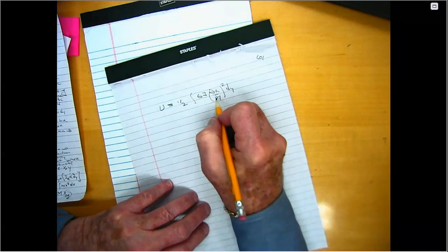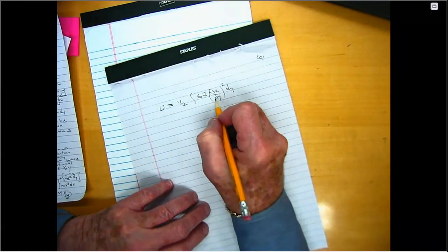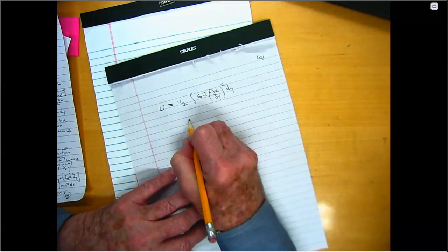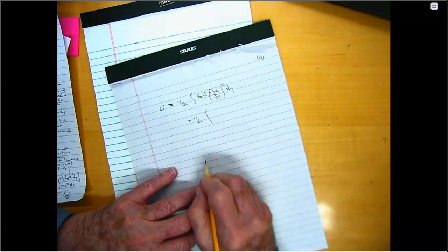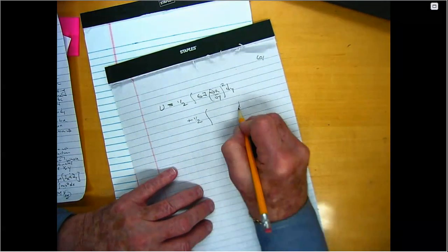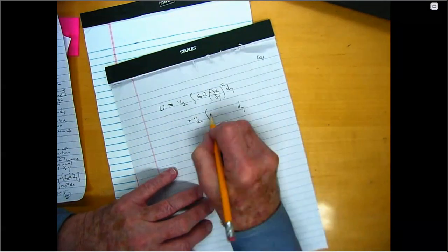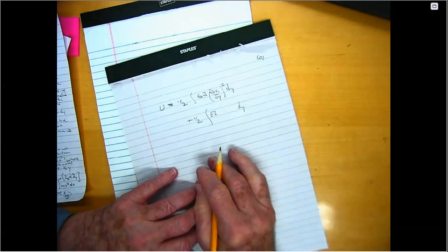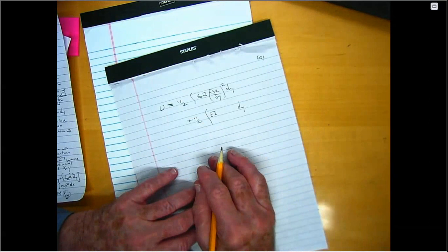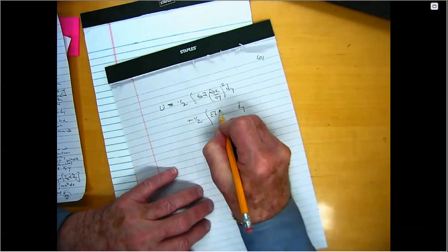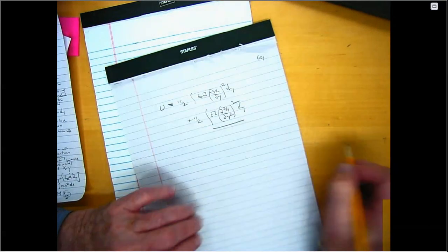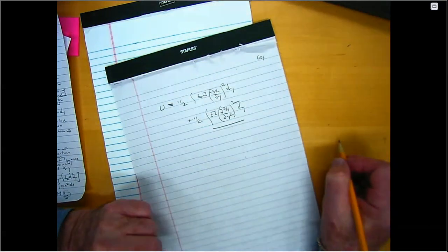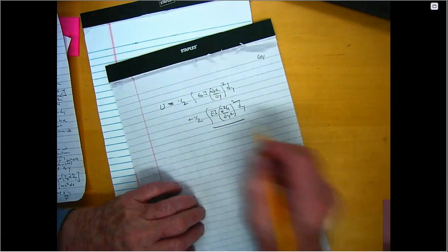It's a partial because alpha now depends not only on y, but also on time, plus something else: 1/2 the integral dy of EI, which is the bending stiffness of a beam, because I'm treating the elastic axis like it's a beam, times the second derivative of h with respect to y squared. This is the potential energy of a beam. Okay? This is the potential energy of a torsional rod.